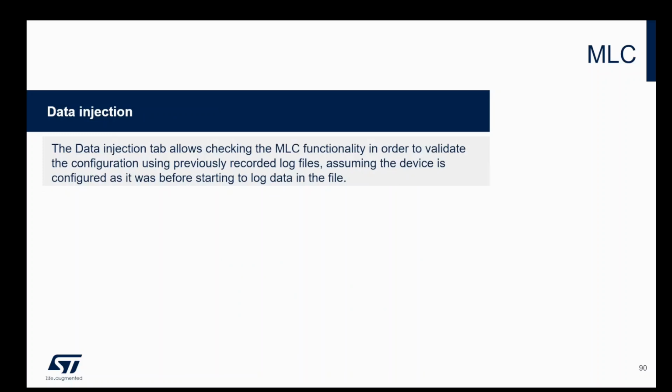MEMS Studio also gives you this very unique capability of data injection. What if you have collected all of this data, labeled all of this data properly, created your decision tree, but it doesn't work as expected when you build your device? So what do you do? You collect data in real time, bring this data, and then on a device like this, you inject the data that you have collected already into the sensor. And you can walk through that and see each step, what the decision tree is doing for you. So that's your data injection. That data injection capability will let you play back your data on the sensor.